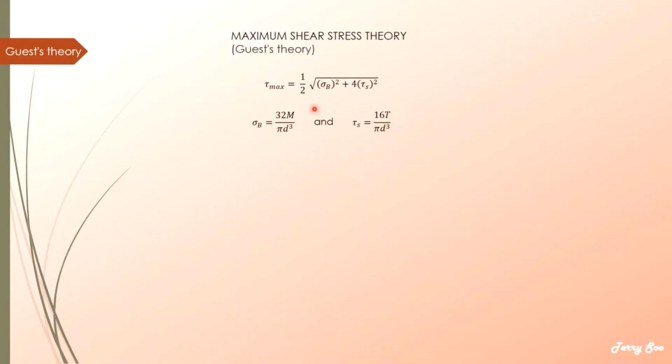So you're going to combine both of these, because when you have a pulley placed on a shaft, first the shaft will be subjected to bending, due to the weight of the pulley itself. Second, the shaft usually rotates, so you have to consider torque, or turning moment, and secondly the bending moment.